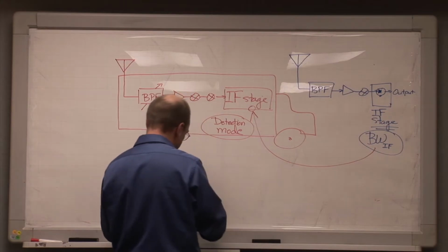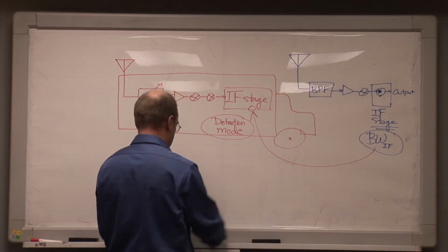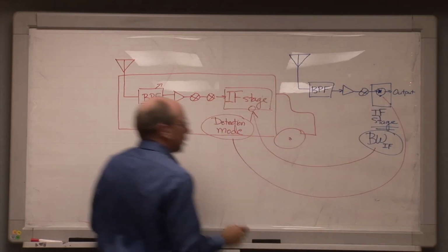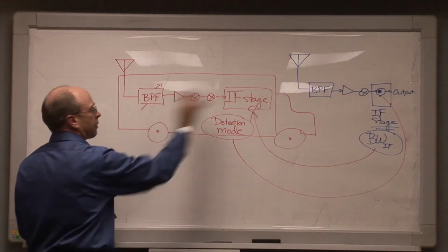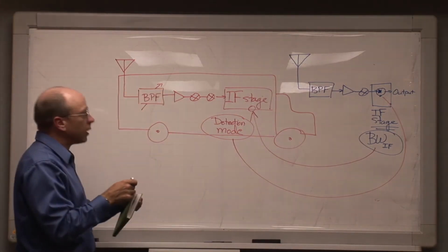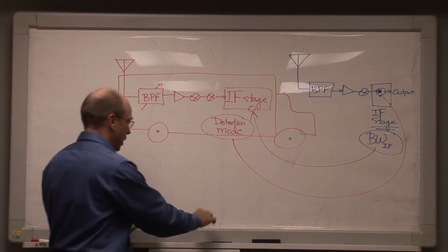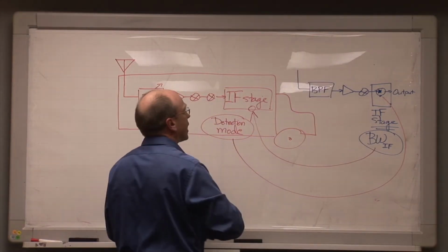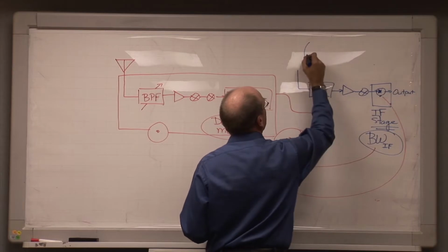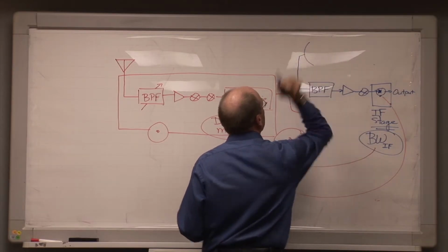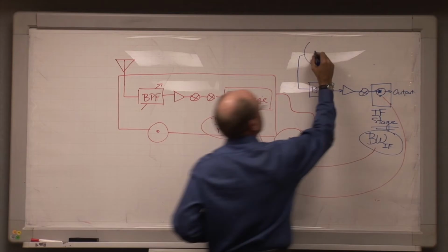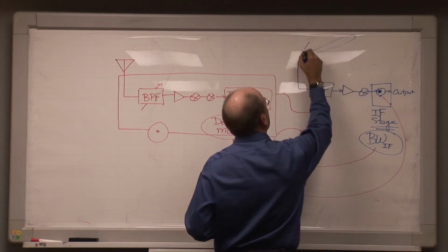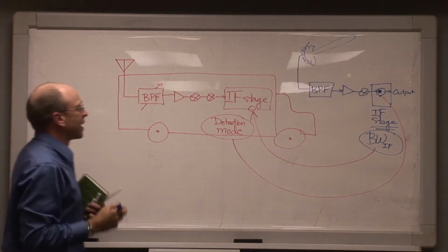So again, we'll connect that up like so. So we make our detection mode look like their detection mode, make our bandwidth look like their bandwidth. We're now closely replicating their system. Now suppose that they are operating here on their front end with some kind of high gain antenna, like so, and they're getting interference in with their system operating with some high gain antenna with a really high gain and pretty low side lobes back here. Well, from our standpoint, that's good.